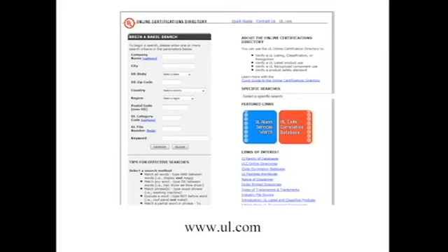They actually test more, or some things that UL does not, such as access doors. If you're looking for a fire-rated ceiling or floor access door, or wall access door, you're not going to find it on UL, not very easily, and very few of them at least. Whereas Intertek or Warnock-Hersey's label, they're the ones that do the majority of the access doors that I've seen.